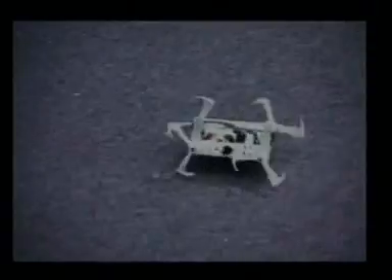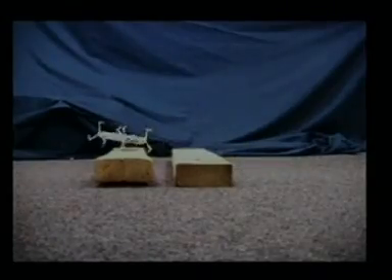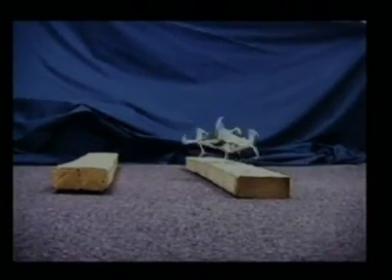To be more compact, Mini-WEGs uses four WEGs that move in an alternating diagonal gait. Like the larger WEGs vehicles, it is battery powered and radio controlled. It uses only one motor to drive all of its WEGs. It also uses one micro servo for steering its front WEGs via a rack and pinion mechanism.